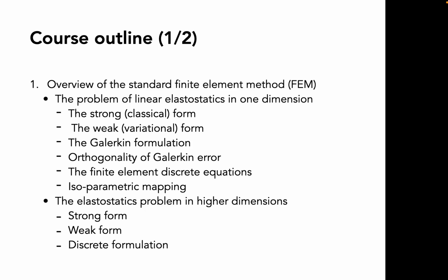Still, this weak form basically satisfies our boundary conditions and our differential equation on average over our domain, right? It's still in an infinitely dimensional space, right? That basically means that I'm not going to get too mathematical in this course, but we're going to look at some mathematical concepts that are important for you to understand the literature. If you read a paper on finite elements, you understand what they are talking about. But the idea is that since we are in an infinitely dimensional space, the weak and the strong forms are equivalent. Okay?